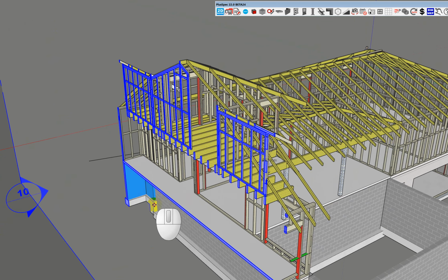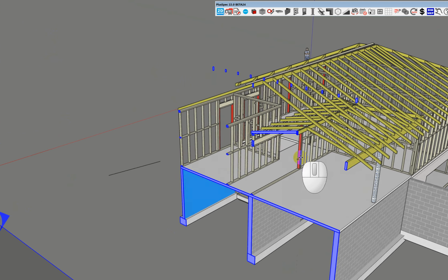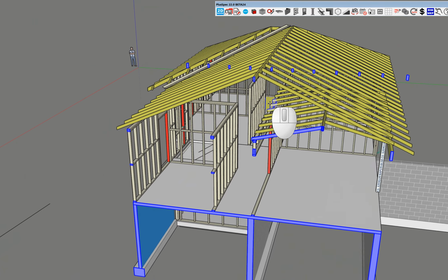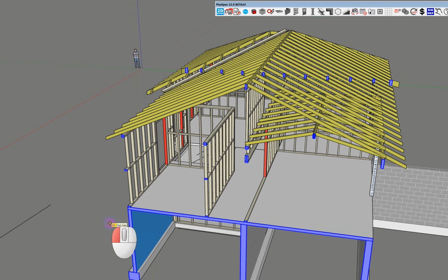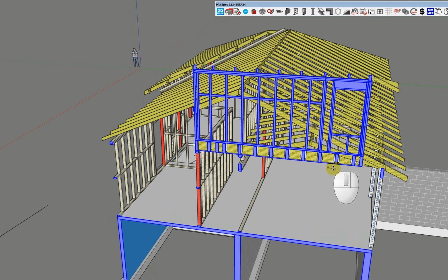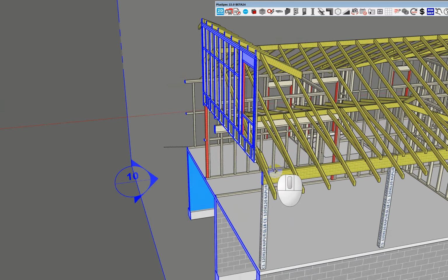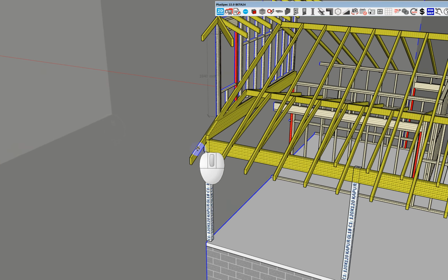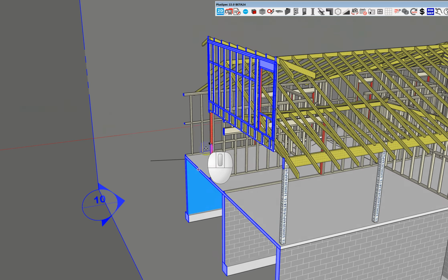As I said before, with the section down here in the roof, we have this big door here with a rake ceiling. I haven't put all the ceiling joists in, just so I don't confuse it, but this rake ceiling is going to bear on this wall here with that large opening, and therefore the beam which is there will need to be booted and another beam run through. The problem with that is that we have to cut the top out of the beam, because it's got to work with the roof line. So potentially it may have to be steel in that location. I don't know, but you can see what's going on there.